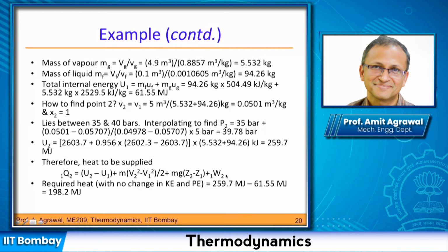Essentially it's P2V2 minus P1V1. Then of course the enthalpy, H2 minus H1, will get involved. But I don't have this term at all. So writing it out as H2 minus H1 is incorrect. The answer may still turn out to be very close, but the idea is incorrect.